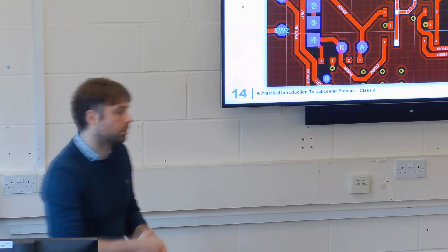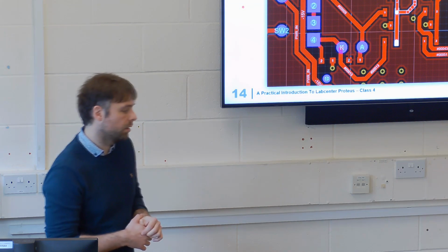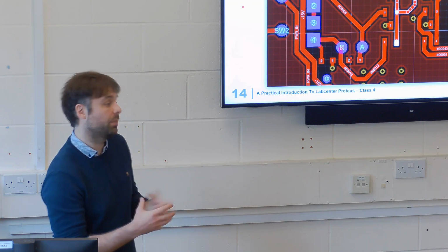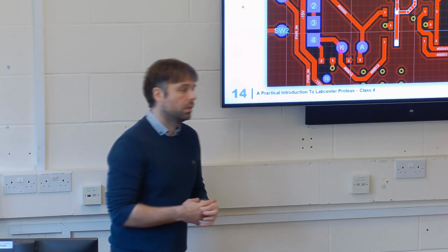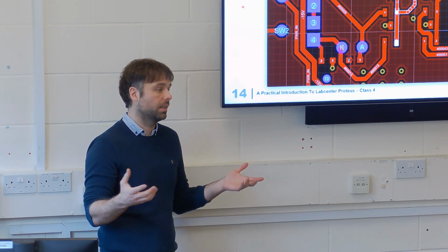What's the drawback of using more narrow tracks for the power? Predominantly, there's two issues. DC resistance goes up, because you've got less copper, so it acts more like a dissipative DC resistor. But also your inductance goes up, which is more of a problem, really. More of a problem than the capacitance model. Yes, for the trace. For power traces, an increased capacitance is actually a good thing, because then it can deliver. It itself is a capacitor, a decoupling cap in a sense.